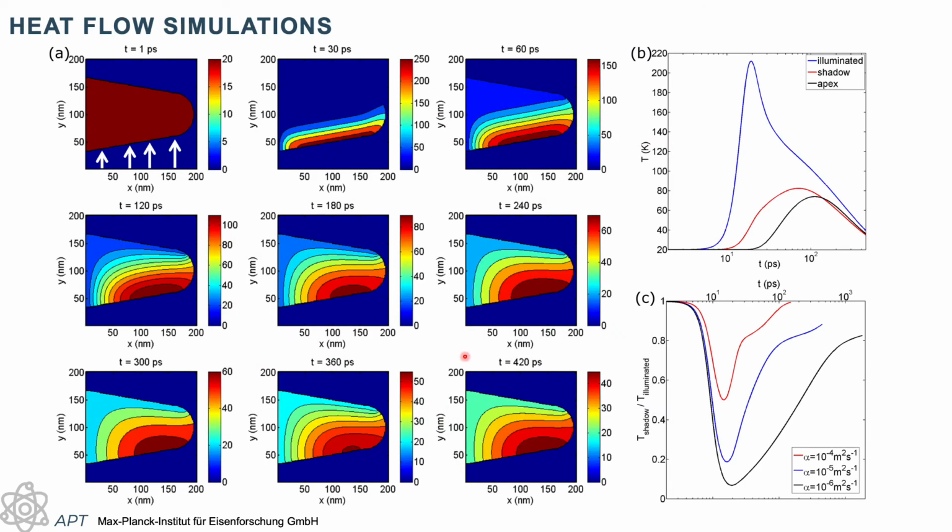And if you do some very simple finite element method simulations of the heat conduction, you will see that there is a very strong difference as a function of the heat conductivity, but also a difference between the different sides of the specimen. And I'll get back to this afterwards, but this is something to bear in mind. Sometimes we end up having specimens that won't be symmetrical anymore because of this.